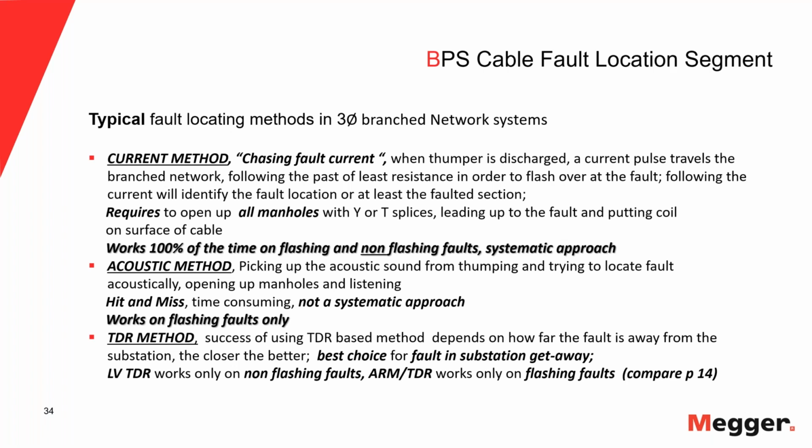Aside from the fact that it's sometimes very hard to locate the acoustic signal. People go down in the manhole, they listen in the conduit, they try all kinds of things. It's a hit and miss approach, I have to say that. It's not a systematic approach, okay? And it works only on flashing faults.